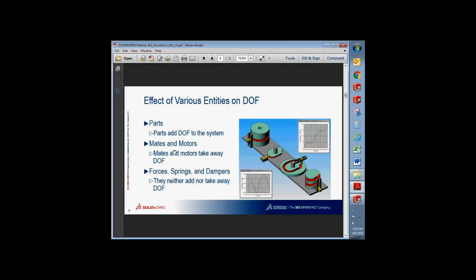But here, since it's a constraint, you're going to put it as a displacement. You'll say move 45 degrees. It doesn't matter how heavy that part is, it's going to move 45 degrees because it's a constraint. Which means when you look at the result, you're going to have a huge force on it based on what the physics is.